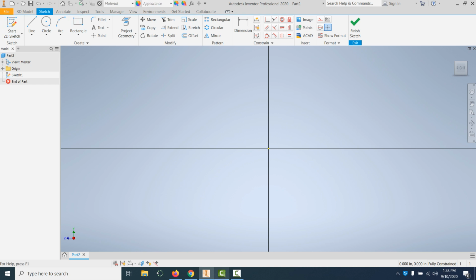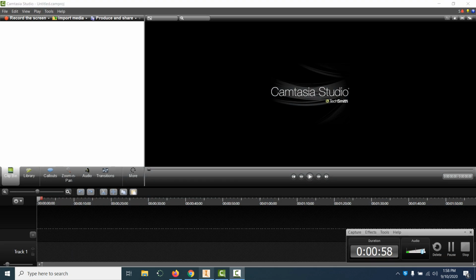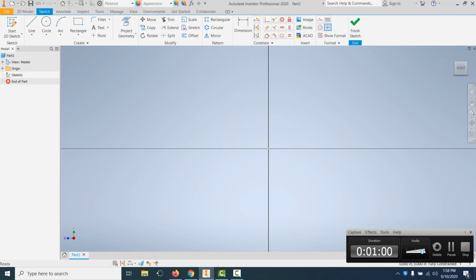With the YZ plane, I want to make sure that we choose rectangle. I'm going to click one time to start, pull my mouse over, and I don't want to be hanging on to the button, and I want to let go of my mouse. Notice that on the right side of my rectangle, it is highlighted in blue. That means that's the dimension I'm going to change first. And I'm going to have to do some stuff on my keyboard to get it there.